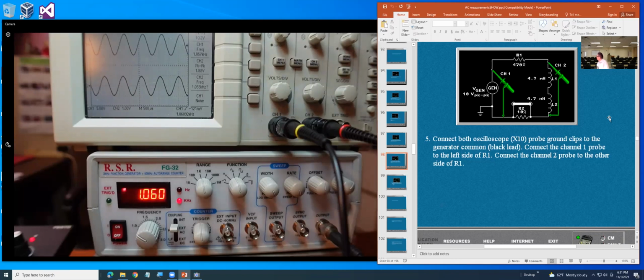Yeah, but how can we do it? You have to set the voltage knobs on the scope, where it says volts per division, to the same setting, like 1 volt or 2 volts, but they have to be the same. That is the first step: set channel 1 and channel 2 at the same voltage.